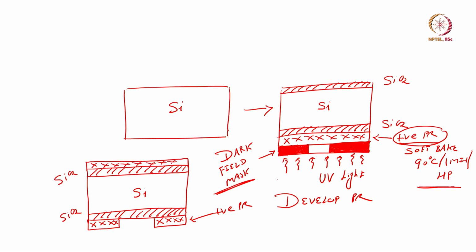So, I will spin coat photoresist on the other side and then perform hard bake. The reason for spin coating the other side and protecting it was to protect the silicon dioxide, right. So, now after this technique, after hard bake is done at 120 degree centigrade for 1 minute on a hot plate.